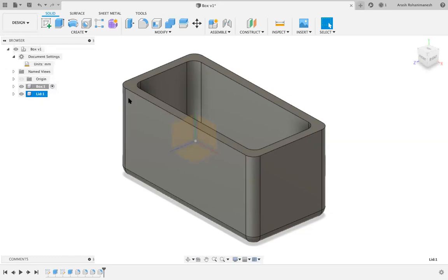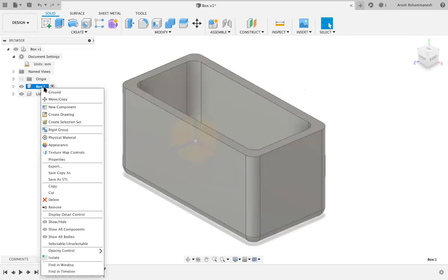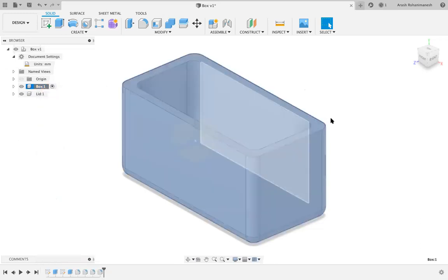So you can select different objects to start 3D printing. These are segmented out, and then you can also copy them and put them in different models. So let's say you've created something that you want to have a different variation of, you can literally select this and copy or move it or whatever you like to do to manipulate it.